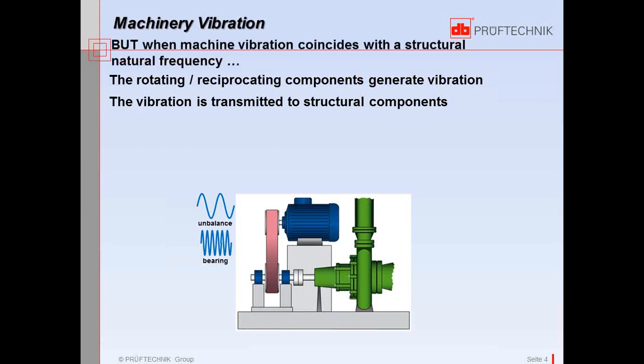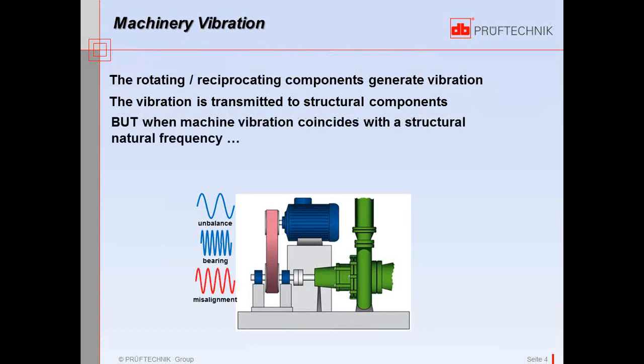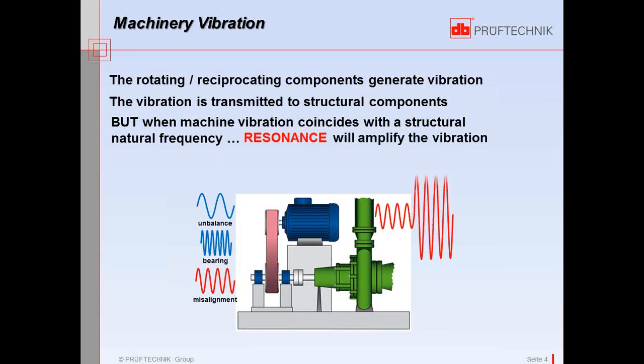And as we know, when that machine vibration happens to coincide with a structural natural frequency, either the base, a fan shroud, the belts, piping in a pumping system, when we have a coincident vibration, then of course a condition of resonance exists, and that will amplify the vibration.